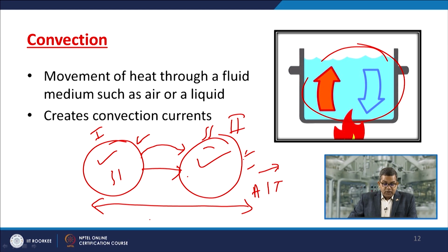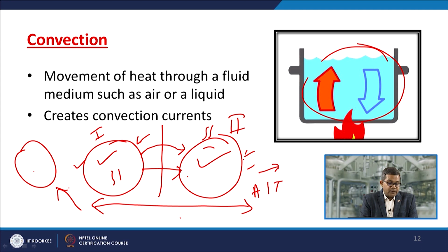So you need to think about how we can eliminate the formation of convective heat transfer, how we can cordon it off once this tank catches fire, and if that is not possible, how we can control the fire. Because if there is another tank, and heat is liberated in such a way that both tanks catch fire, then the excess amount of heat may propagate the fire to tank number 3. So one must know how to control this aspect.